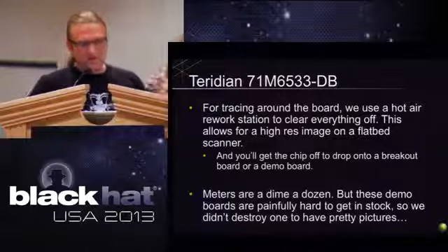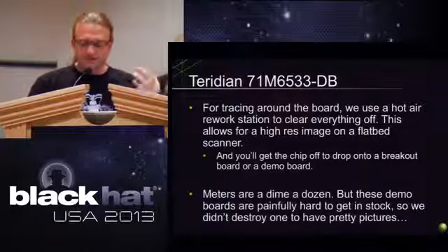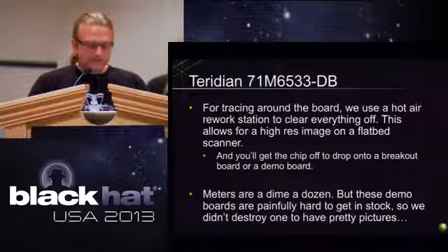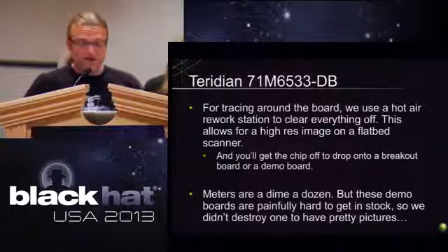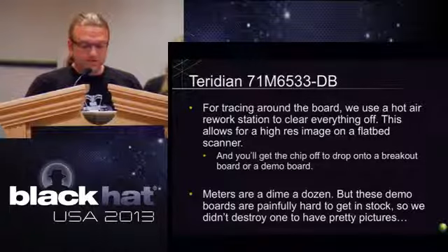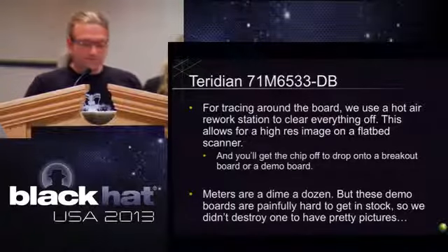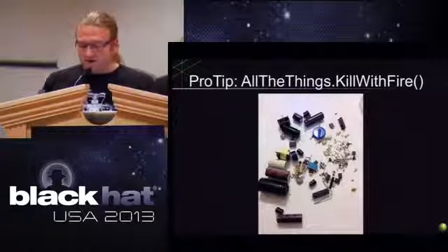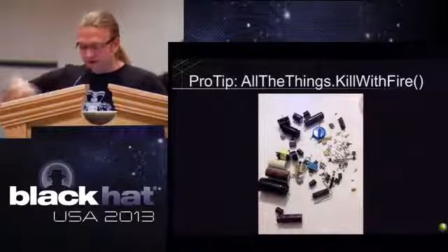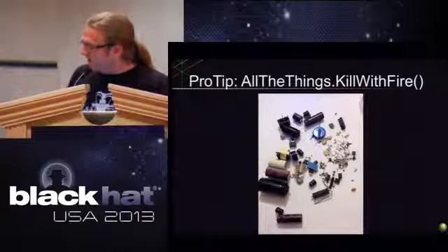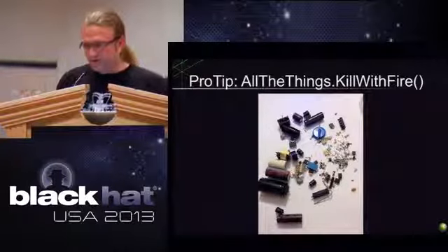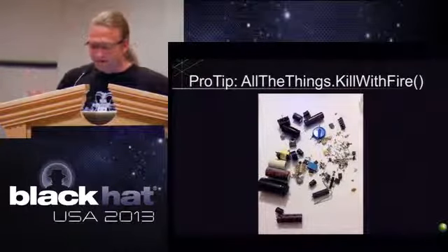Second thing, when you start wanting to look at these type of devices and how they work, you really want to figure out what the PCB is doing around the SOC just as much as you want the SOC. One of the tricks that we have started to do more and more is I take a production board and I desolder everything. That's all the detritus that was on the board. I'm sure it's important for it to run, but I don't care at this point. I take that, I throw it away.